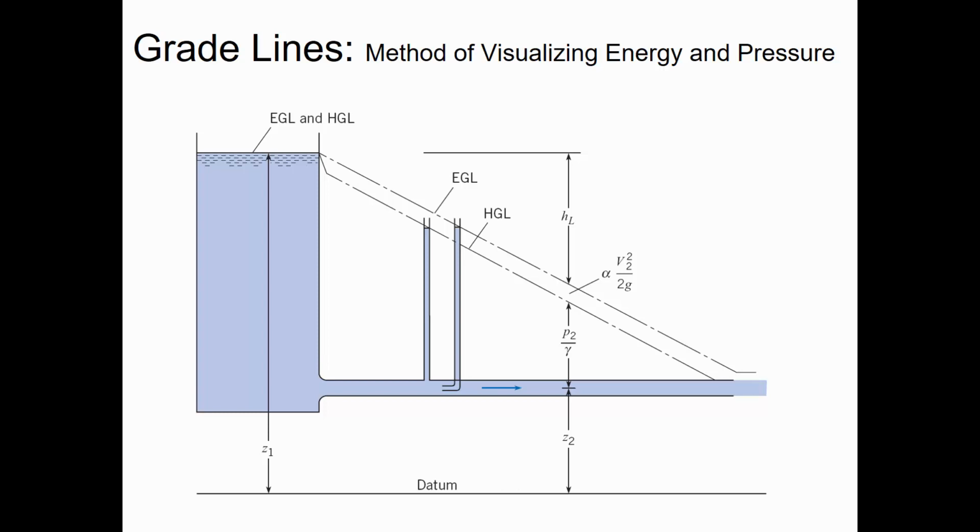In fact, there are some water treatment plants in the West where the water is coming from an elevated mountain reservoir, and they don't have to have any pumps in the system because they have designed the layout so that everything's downhill and there's enough energy from that downhill motion that they don't have to move the water by pump. When they create plans, they'll sketch out how much energy is in the water and what the elevation of the water is as they move through the treatment plant, so you can see how much pressure there is. And that's what this is representing.